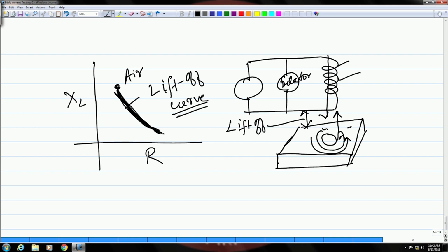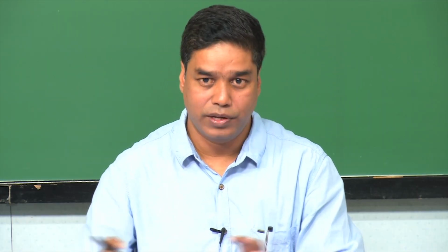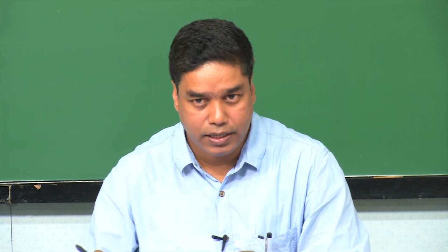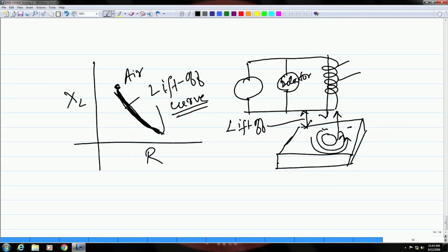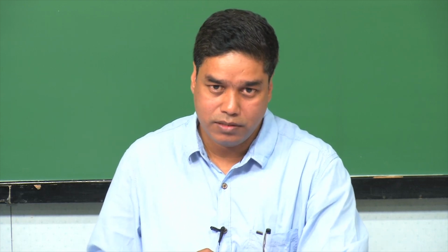Okay. So, that means this will tend to go back towards lower value of R, and now you have less eddy currents flowing because of the presence of the crack. So, the magnetic field of the eddy currents will also reduce, and as a result the XL or the inductive reactance would also tend to go up. Okay. So, that means the crack signal will be like this. So, you will immediately see a spike like this the moment the coil or the probe encounters a defect.